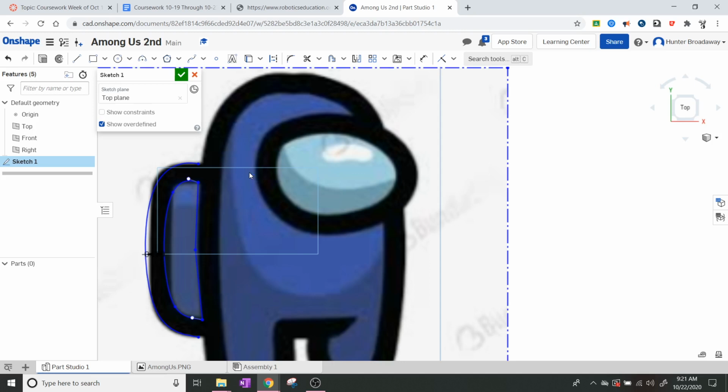Yeah, try not to. Okay, so guys, y'all need to make sure that you're selecting the actual side of the sketch. Make sure that you're actually just clicking just the spline part. Don't click on the whole thing because it doesn't know how to deal with splines very well. Yeah, once again, that's an undo. You're going to have to play around with it a little bit. This isn't something that is just going to automatically work. So click on that. Okay.